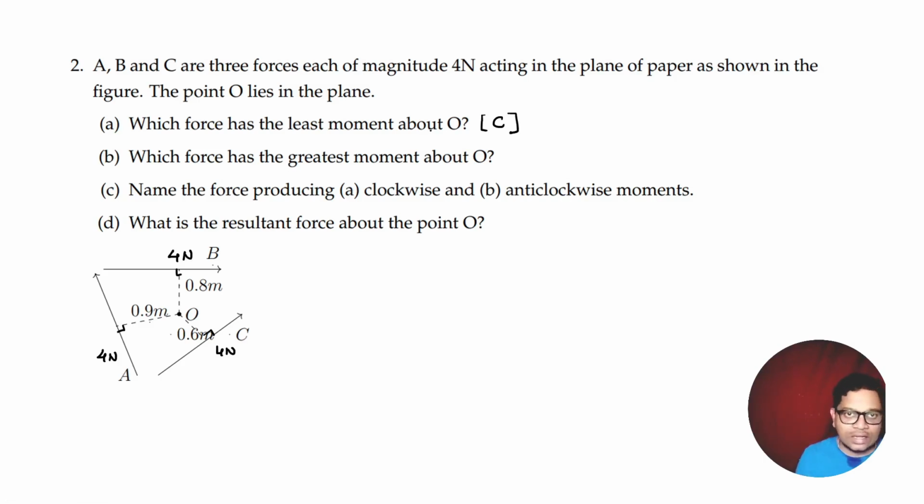Which force is the greatest? Again, going by the same logic, it will be force into the perpendicular distance. Since the force is the same, we will look at the longest distance, that is 0.9 meters. And that answer is A. Force A will cause the greatest torque.